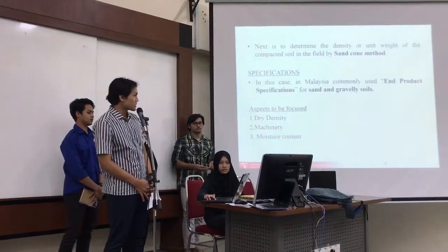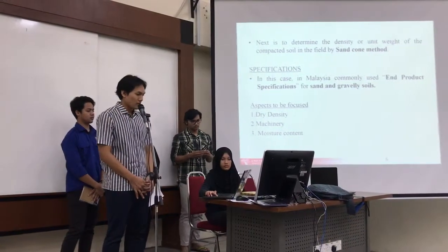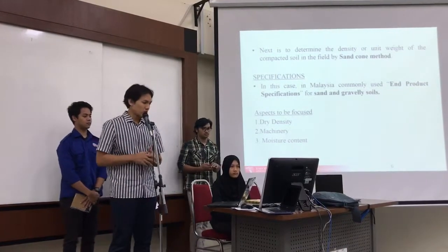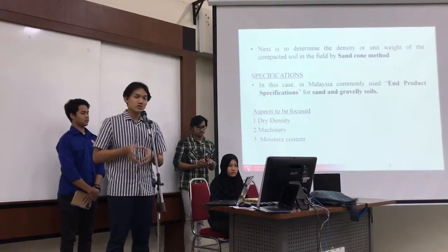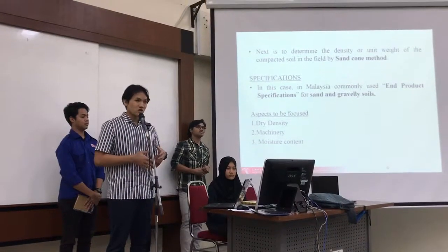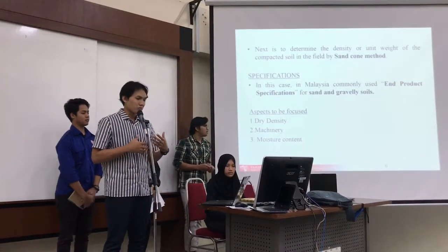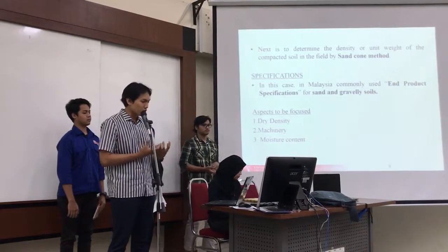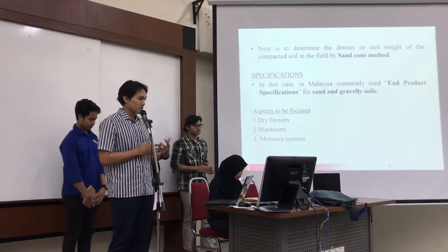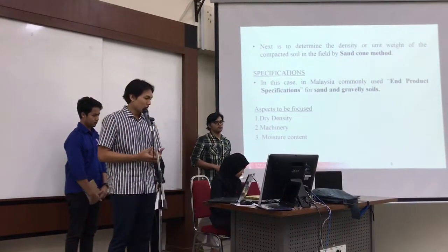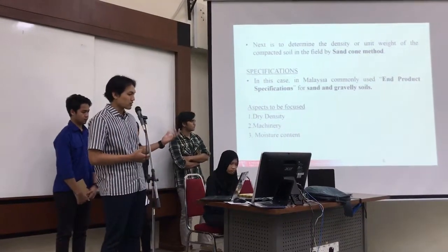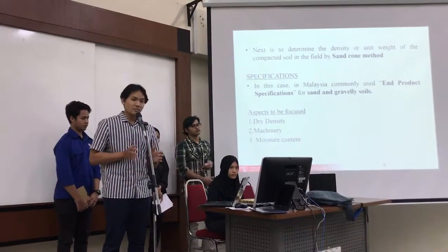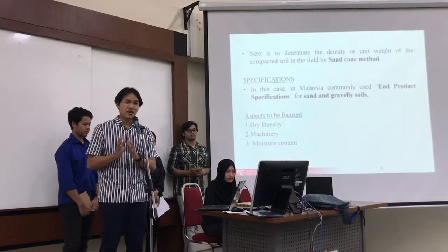And last but not least is moisture content. Moisture content is very important to distinguish compaction from the consolidation process, which is a geotechnical process of expelling pore water from the voids as a result of volume reduction under external static loading on the soil's self weight. The limits of moisture content during field placement are also a vital aspect that needs to be specified.